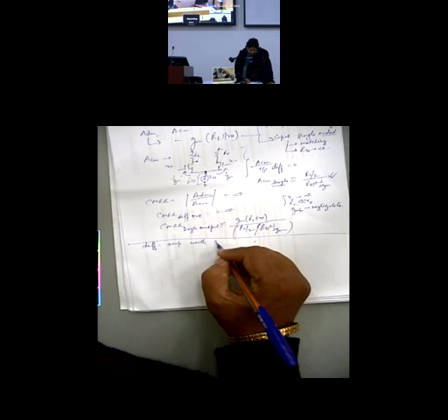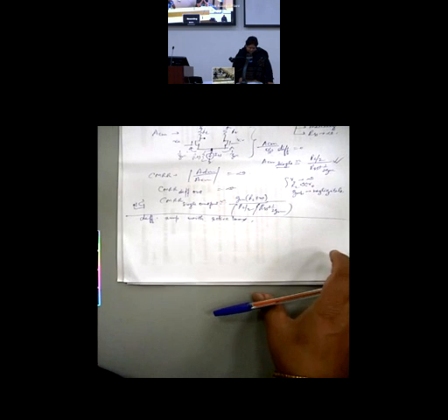Now we move on to the next, that is the load. So now I come to the current differential amplifier with active load. Now it is a special term. You can say I can replace RL by a diode connected MOSFET. It is an active load. I agree, no issue here. Similarly, I can replace with a diode connected PMOS, NMOS, current mirror. Okay, I agree, these are all active loads. But a special term for which this active load differential amplifier is reserved is for a given specific topology.